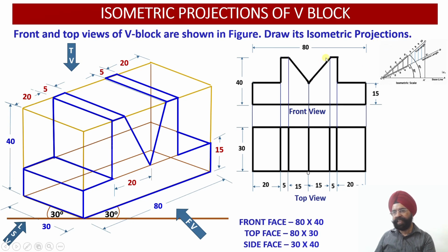That is, this is the surface. Please check, this is the surface which is having these two starting points. This is my starting point which is lying over here, at a height of 15 millimeter, and this is going to start 20 plus 5, 25 millimeter from this end. So this slant edge has been joined over here, but I have not joined the back side of this slant surface. So I need to join the back side of this total slant surface. This slant surface will also be having the back end.